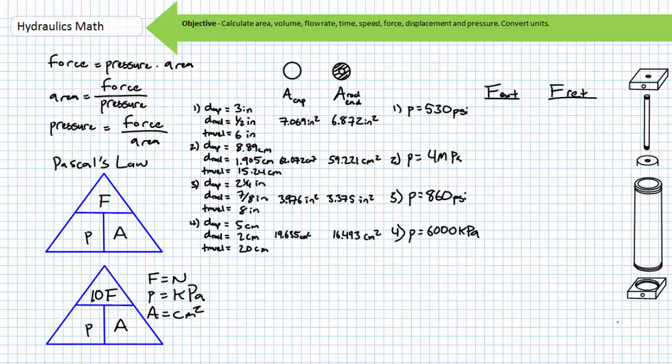As we'll soon discuss at great length in the Pascal's law lecture, the force of extension exerted by a hydraulic cylinder is governed by the pressure input to the cap end of the cylinder and acting upon the full cap face. Similarly, the force of retraction is governed by the pressure input to the rod end of the cylinder and acting not upon the full cap face, but rather the full cap face with the central portion removed from consideration. At retraction, the input pressure acts only upon the smaller, ring-like rod end area, not the rod, the ring-like portion. Pause to consider what this implies.